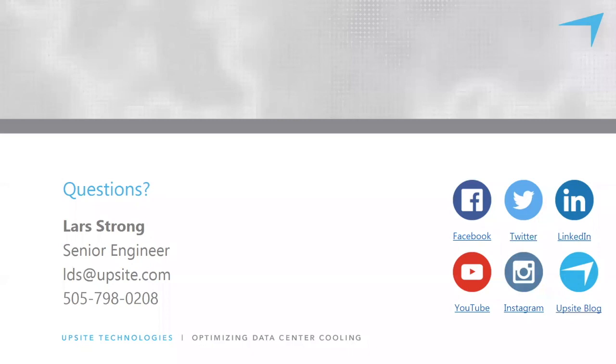And that again is very easy. You just look at the display for the cooling unit and you can know what the supply air temperature is, or measure it if it's an older cooling unit that doesn't tell you the supply air temperature, and then compare that to the warmest inlet air temperature to the IT equipment, and that'll give you that delta T.